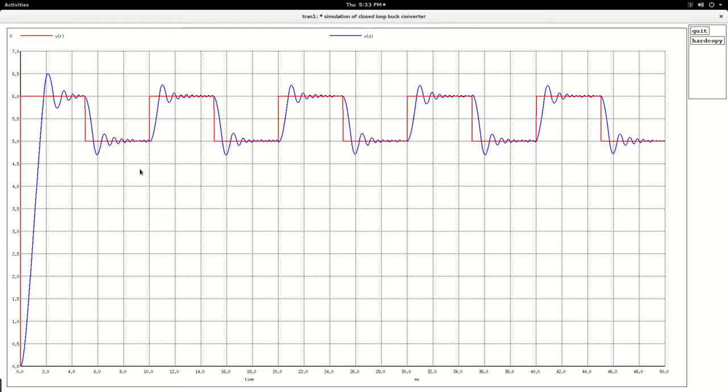Of course, I will leave it to you to play around with all the different parameters and also the parameters of the buck converter, L and C, and just try out. This pulsed kind of a reference is just for the purpose of learning, so that you see that there is some effect. The output is trying to track the input and output is coming to a desired value. In practice, it will be constant.